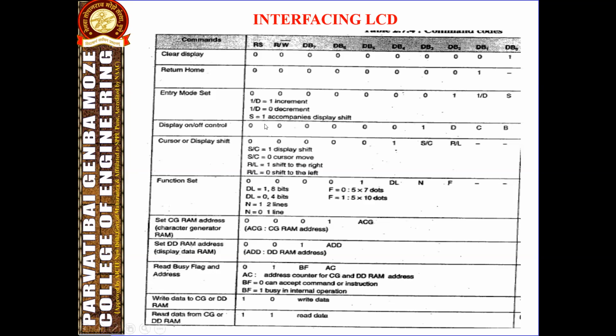This is the entry mode set. In this, we should make this bit increment or decrement. If we make it 1, then it will increment, and if 0, then decrement. The S bit is the one accompanying the display shift. This means that it sets the direction for moving the cursor and specifies the shift of the display. These operations are done during data read and data write.